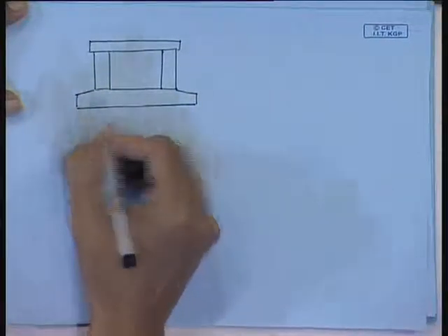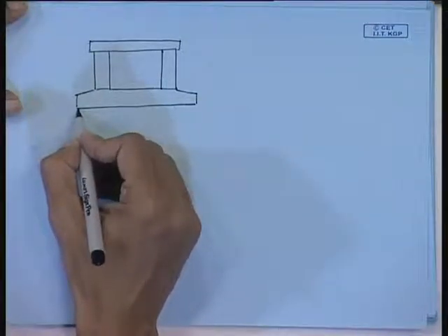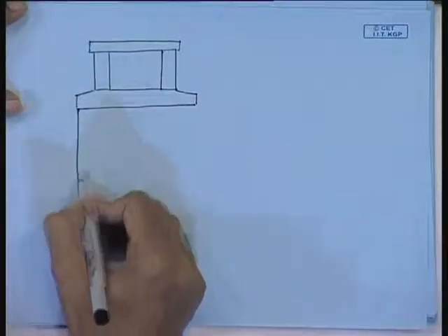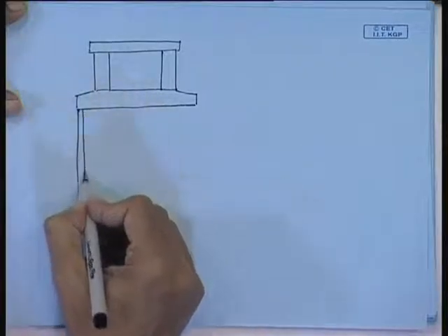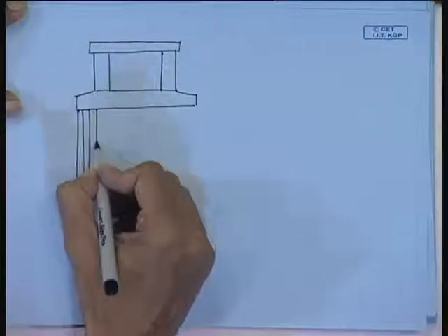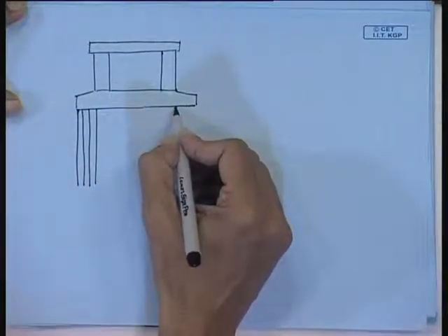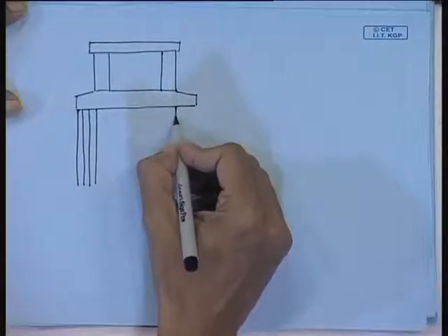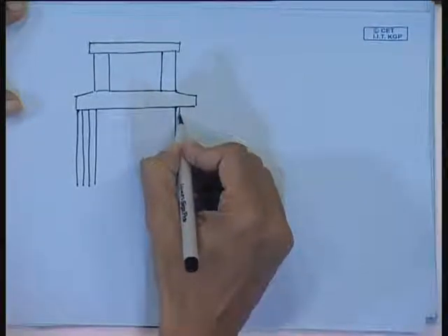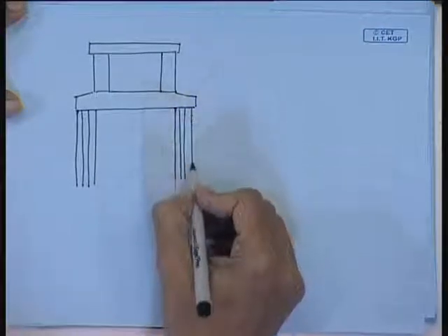Now, the basic reason I told you is because you want to increase your tendon spread. Later on you will find that if you increase tendon spread, then you can reduce the pitch motions and also your vessel offset. So, this is called your extended leg TLP.